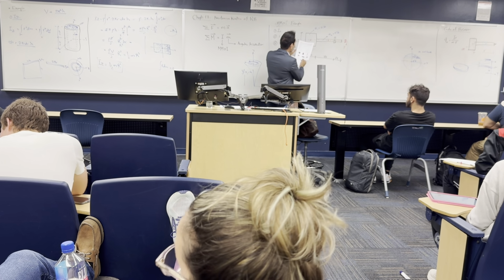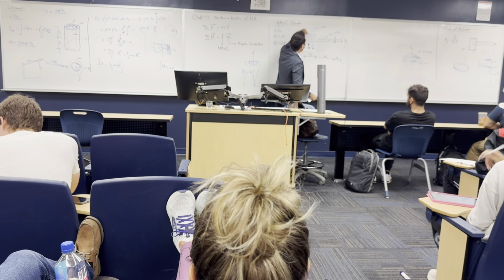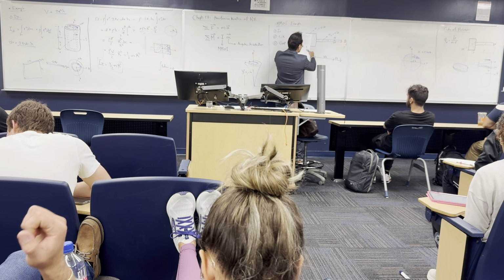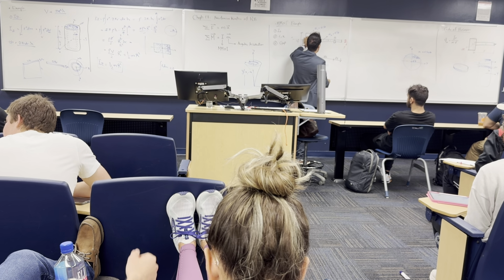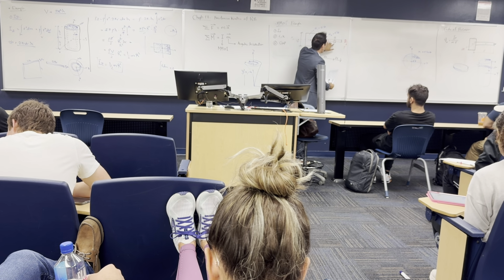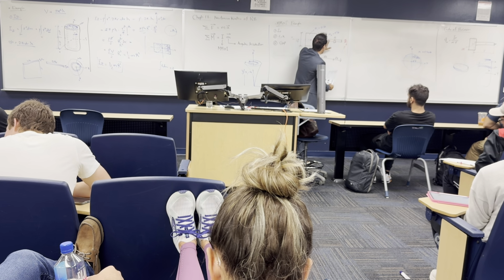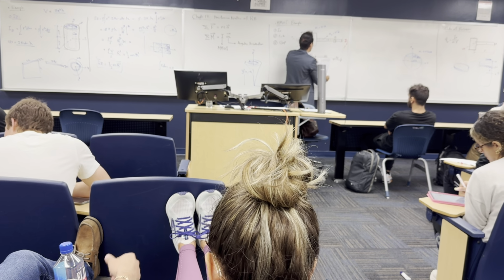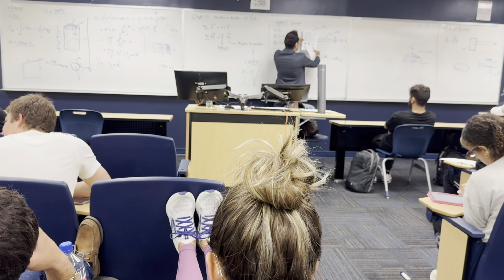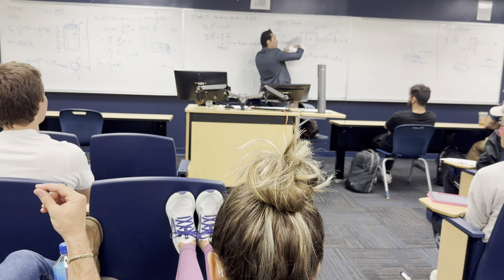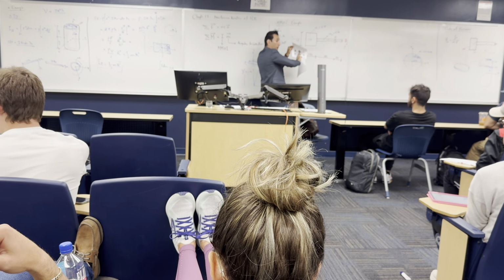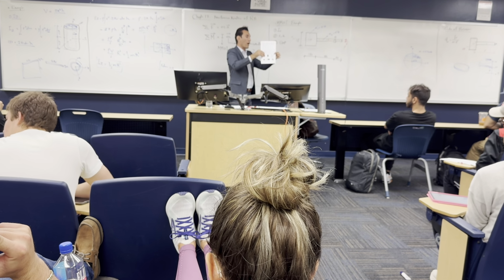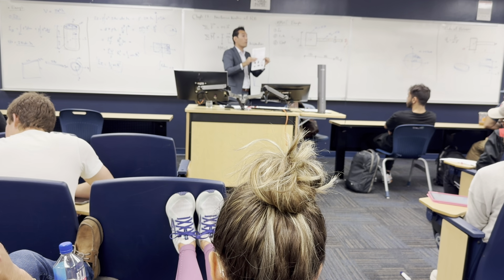All right, so here if you look at this one, let's assume that this is a plate, and we are looking at how this plate is rotating about the CG this way, so we need to find how this is going to rotate here and then transfer it to this, because we are looking at the moment of inertia about O. Same thing, we're going to look at the moment of inertia about this point and then transfer it here, and this point and then transfer it here. So we're looking at the moment of inertia, how this body is moving this way, so I need to find the axis perpendicular to this point. Not X, not Y. Not how this body is going to rotate about this way, or how this body is going to rotate this way. And that's very, very important because you are given